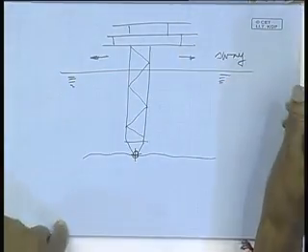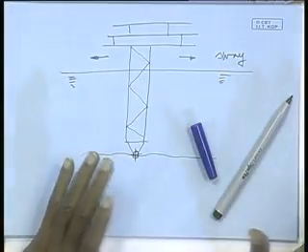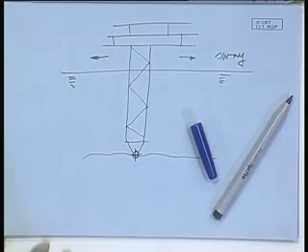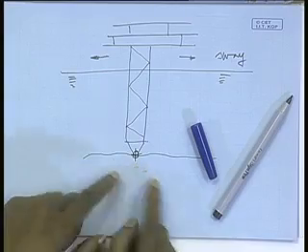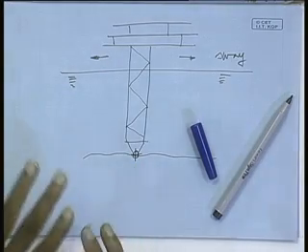That means in this way the whole structure has been made lighter. The entire platform, or the platforms, the decks, because these are the decks, will house the required machinery, equipment, etc. That is mounted over a tower, and the tower you can make much longer, much taller, so that you can go to a greater depth, and it is hinged at the bottom so that it has a freedom of movement. This is very schematically drawn.